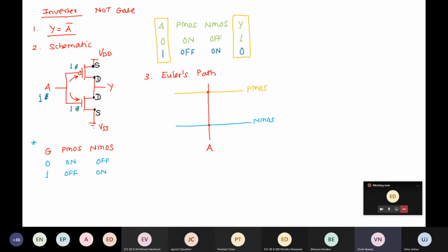Okay, so now looking at this, the drain terminals of the PMOS and NMOS are shorted together and form our output. Am I right? So we will have our output. Let us assume this is a drain and this is a drain, the right-hand side of the polysilicon is the drain. I repeat, this is assumed, and both of them are shorted together. So I made this connection and this is going to be our output. The remaining terminals will automatically become sources.